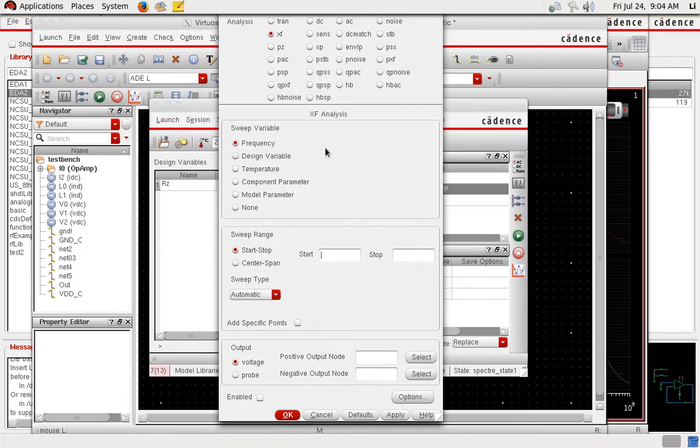Okay. It's actually, if you want to find a way to intuitively understand it, I think XF is more like maybe the counterpart of stability simulation. Okay, it's not accurate, but somehow you can understand like that. All right. So the frequency sweep range, we're gonna do it starting from 1 Hz to 1 GHz, and I'm gonna use a probe to probe the resistance.